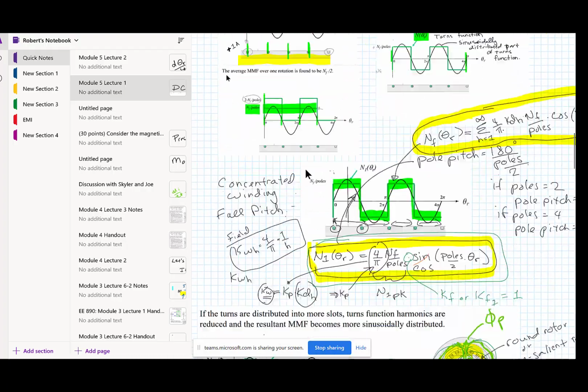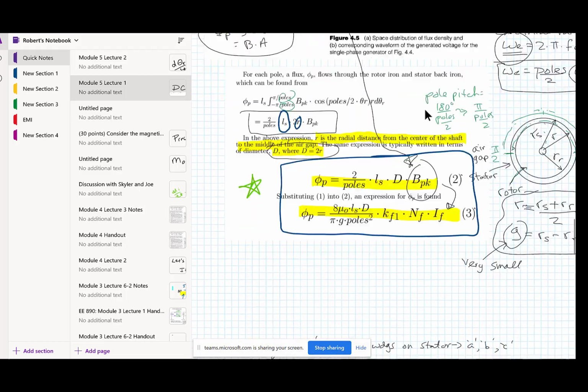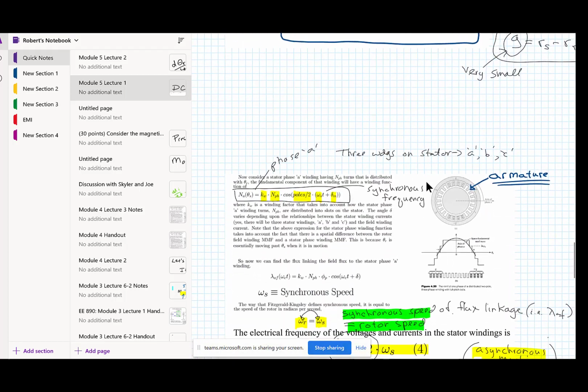Try to show you where that's on here. Right here. See, there's now windings on the not moving part, the stationary part. Notice all those empty slots, but there's these 1/3 of the slots are full. That's because we're going to have a three-phase machine here.